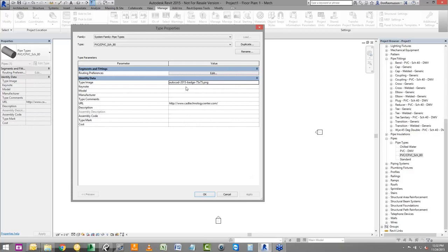If you're using Revit keynotes, here you can come in and add a specific keynote to this pipe type that you want to be populated whenever this pipe type is used. This requires, obviously, editing the outside file for keynotes inside of Revit. You can then add a model number or a manufacturer, so say for example Spears. Any comments you might want to add here as well.